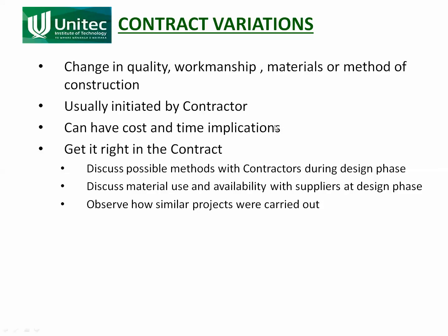So all contractors do things differently, and oftentimes during the construction they'll be proposing variations on the specifications, and that needs to be considered by the engineer because obviously you want to build it quickly and more efficiently. To try to minimize the amount of these contractor-initiated variations, you want to discuss the methods with the contractor during the design phase.